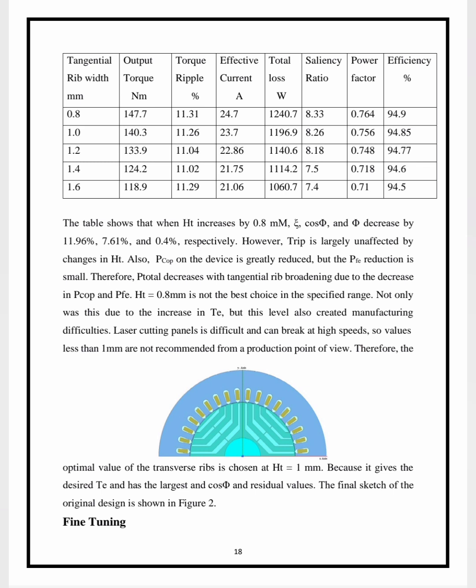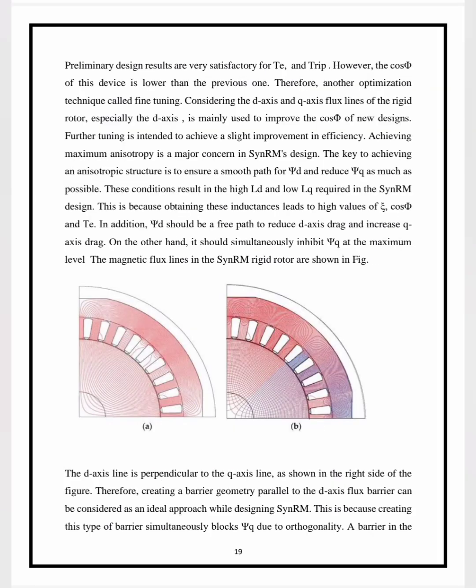Also, we will see how fine tuning is an important technique in determining the efficiency of synchronous reluctance motors. The preliminary design results are very satisfactory for output torque and ripple torque. However, the cos theta of the device is lower than the previous one. Therefore, another optimization technique called fine tuning came under consideration.